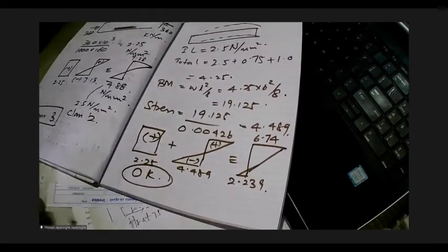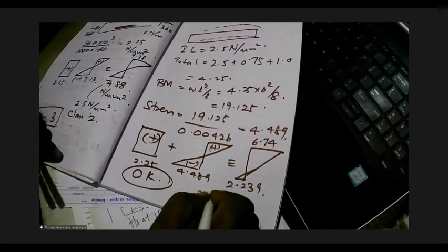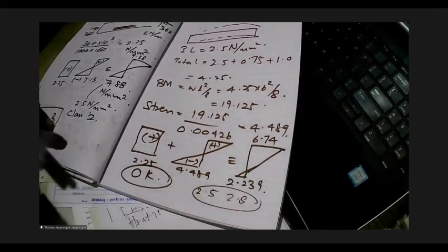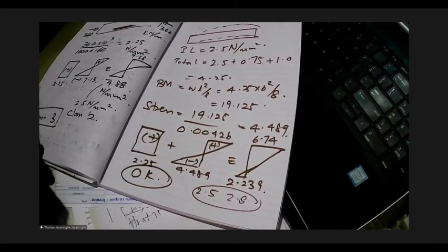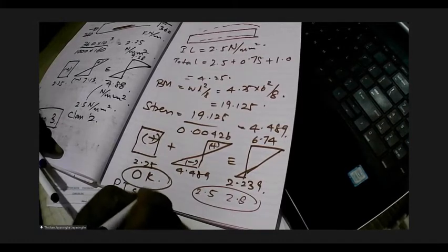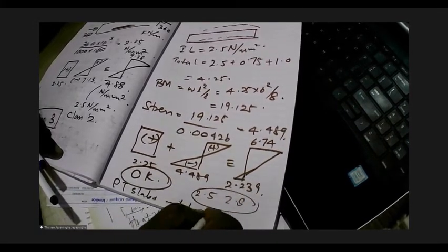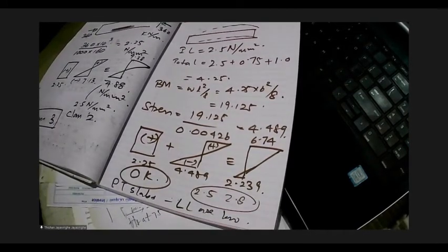Now you can see, okay, we can allow about 2.5 to 2.8 type of stress in the slabs. So what this means is PT slabs are good when live loads are low. PT slabs are generally used in car parks, office buildings. But if you try to use PT slabs for a place where you can get crowd loading, then you have to think of going for slightly higher pre-stress. Is that clear, Bashita?